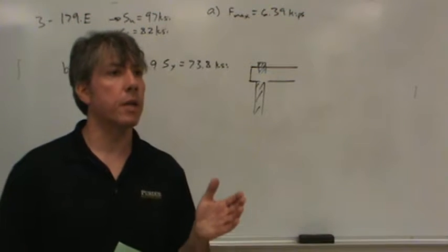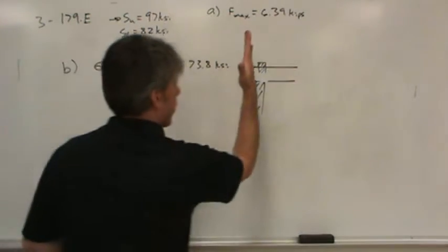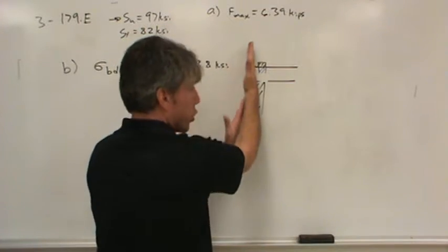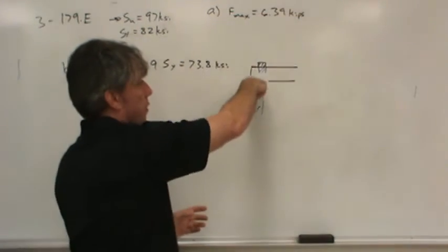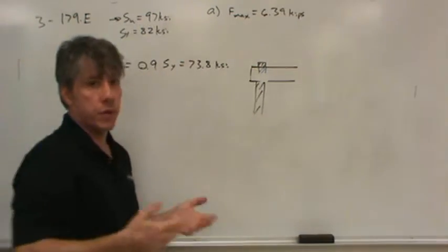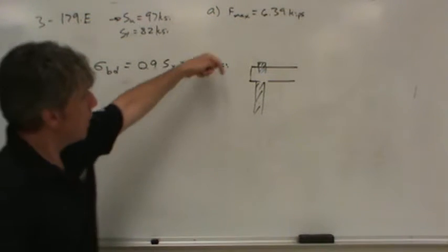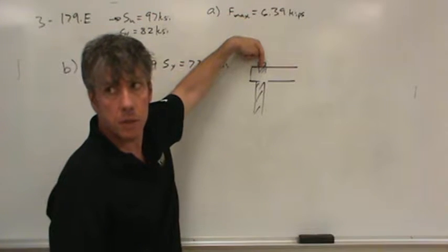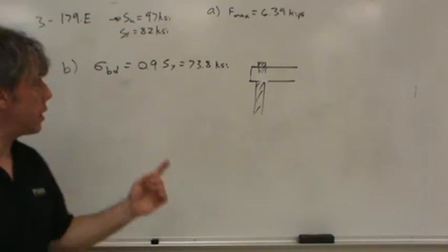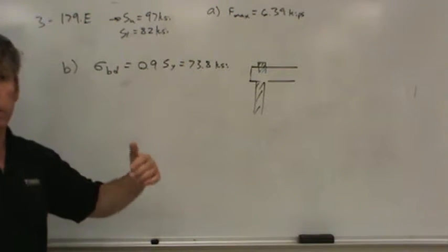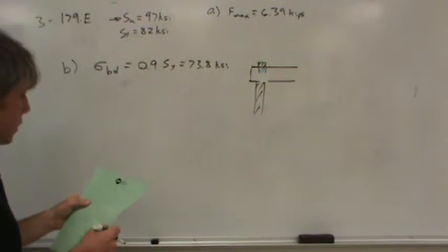The reason we use tau is because there we're talking about shear. Did you notice that the area we were talking about was an area of the pin like this, and the link plate would shear past it, right? So it's kind of like a scissors motion. Okay, so when the direction of the load lies along the surface, in the same direction of the surface, if you will, then that's a shear. In this case, the load is normal to the surface. Does that make sense? It's applied to the surface normal. And so we're talking about what's called a normal stress. So anytime you see a sigma, you know we're talking about a particular direction of the load relative to the surface that would fail. Okay? Same thing with the tau, but they're opposites of each other.